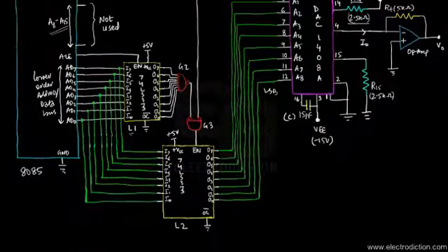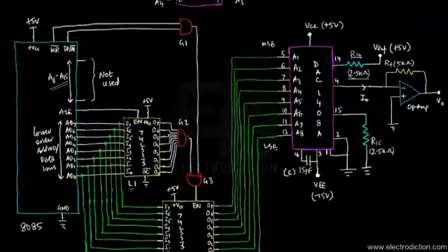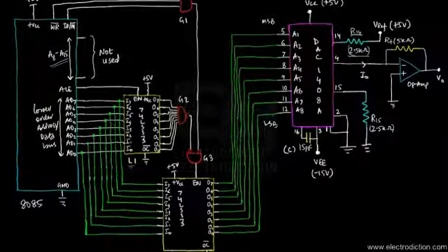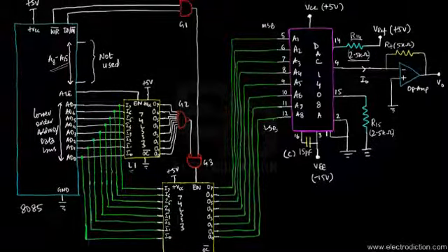And in order to provide the other input of G3, we've used an AND gate that just takes in the write bar and the input output memory bar signals of the 8085 microprocessor as inputs. That's gate G1. Alright, so that was the entire description of the hardware involved over here.